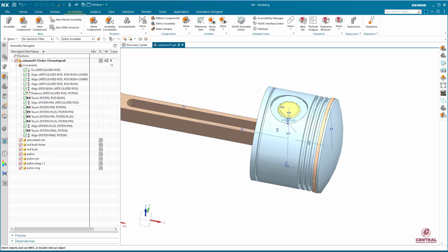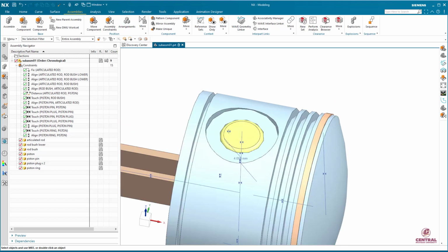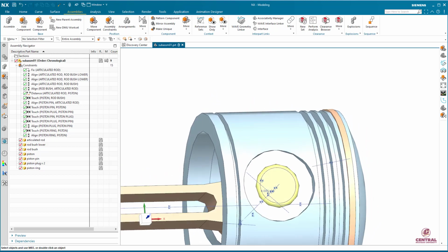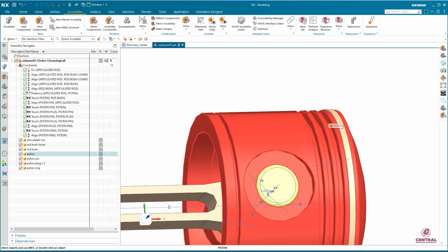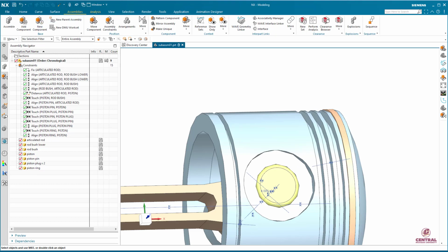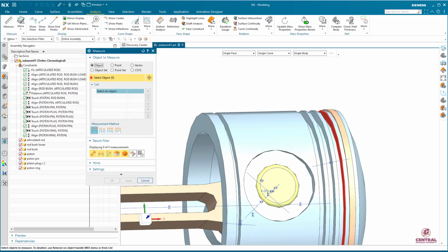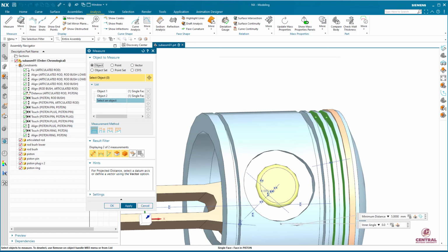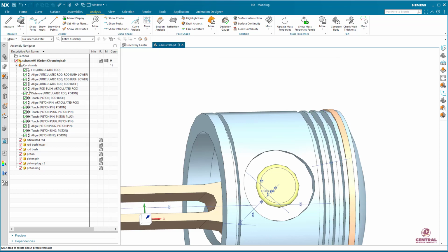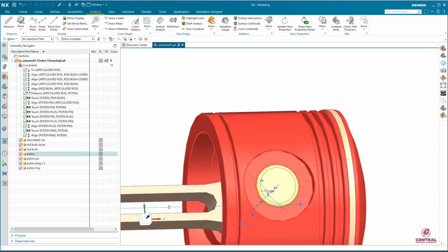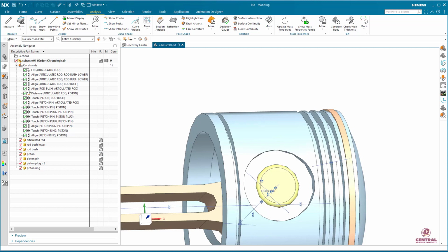All right, so I'm going to do the pattern, but I need to know the gap, right? I need to know how much from one to the other groove. So I'm gonna again measure from there to there. Well, according to this measurement, there is 5 millimeters of gap there. So if I repeat this with a 5 millimeter, automatically it will be there with this direction, which is linear in this case, right? One directional repeat. All right, got the idea.